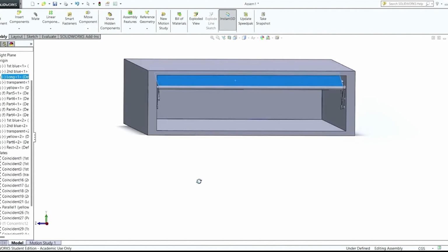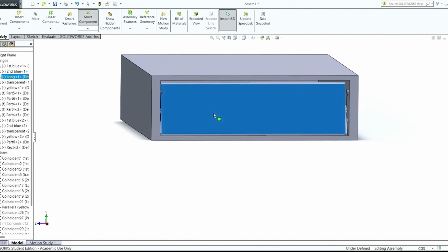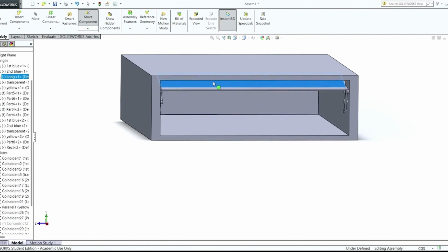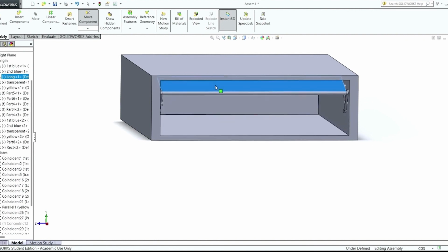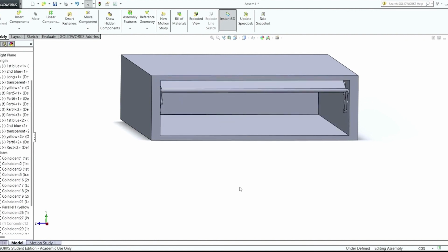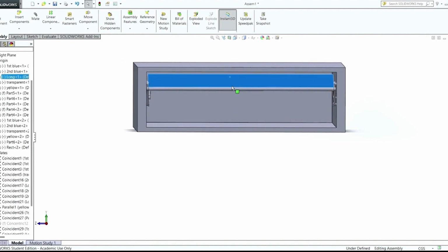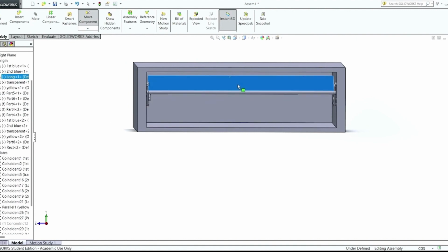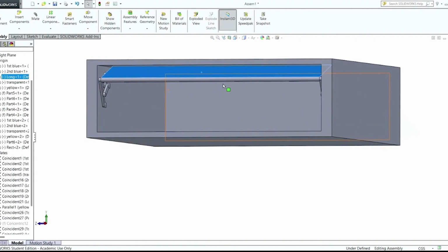Initially, the garage is open, that is, the vehicle is inside, and the garage door is parallel to the rooftop. Now, the mechanism is utilized to move the garage door so that the garage is closed. This is a guidance problem, where we want a rigid body to move from the closed position to the open position in a prescribed manner such that it does not hit the body of the vehicle.